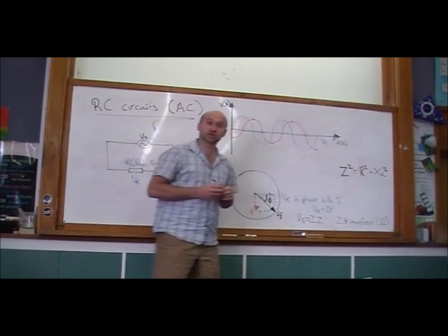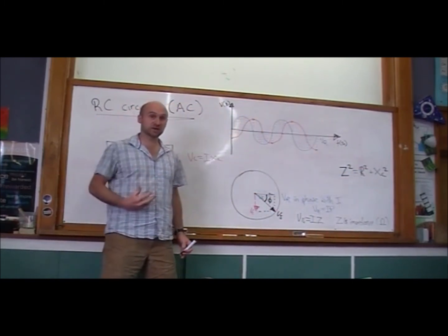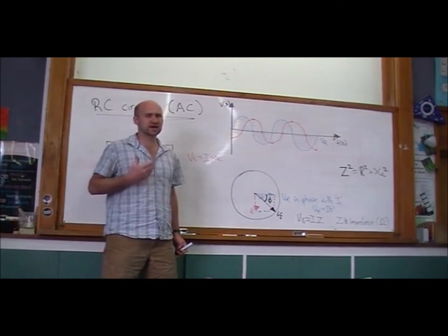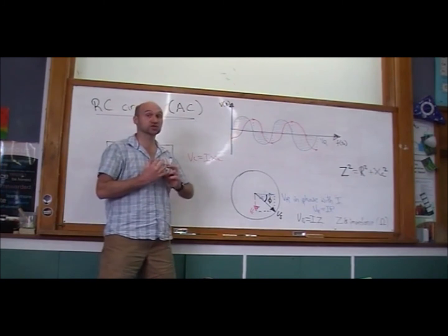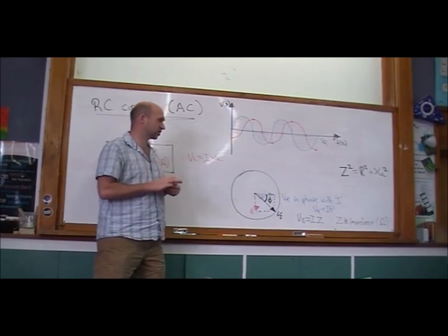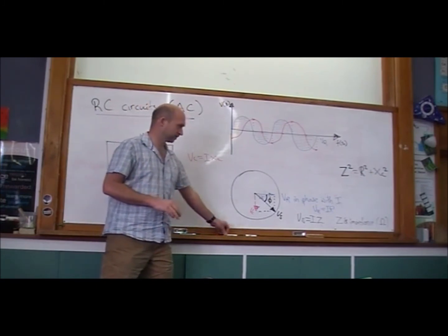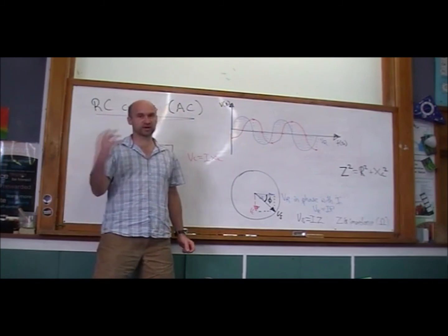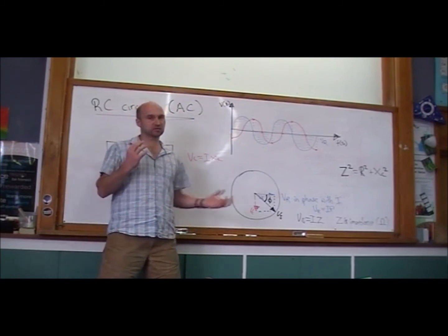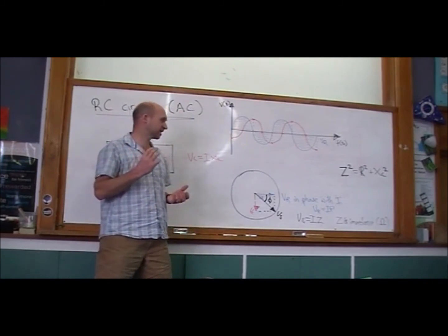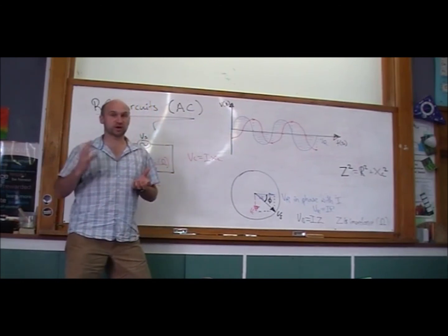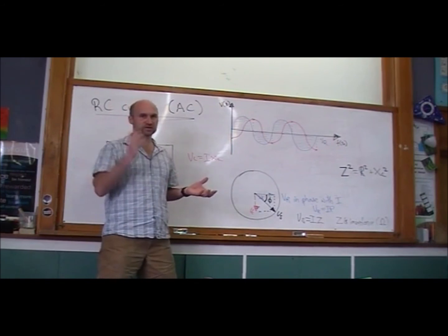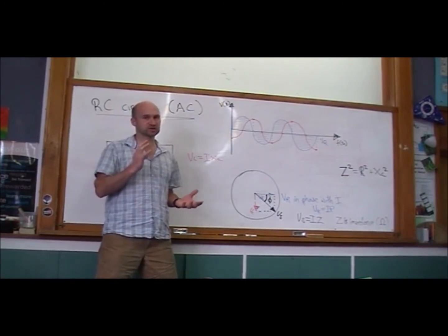There is also a voltage across the capacitor, which is also proportional to the current, but that's not dissipating heat, that's just the capacitor acting to store energy in the circuit. The impedance is the combination of the resistance and the reactance of the capacitor. We can use that to find how the total supply voltage responds to the resistive and reactive components of the circuit.